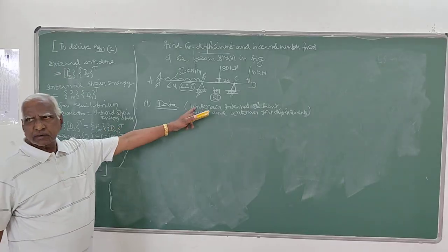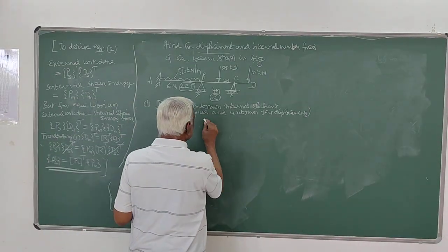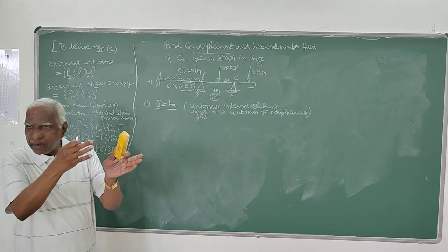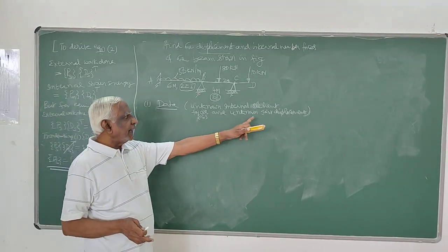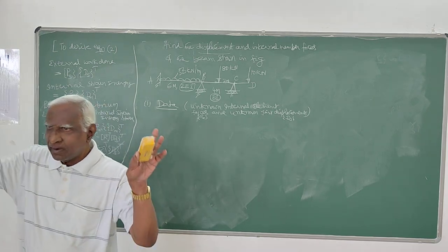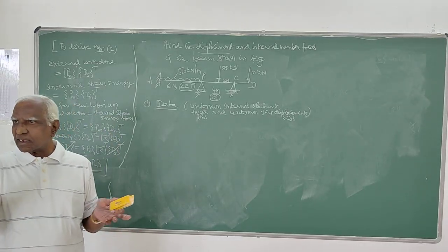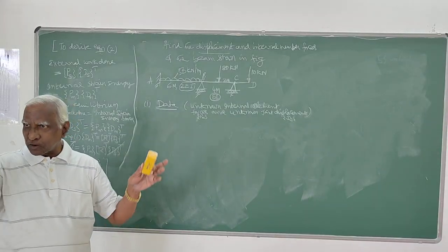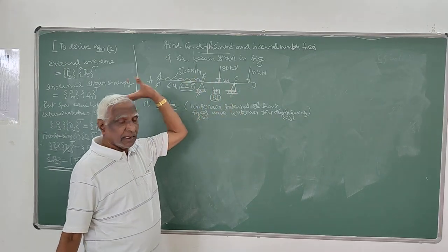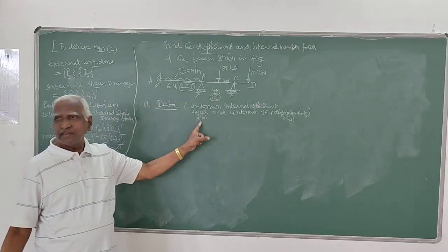That's what we have to determine. The data for calculating the unknown internal element member forces. Element member forces means it is PM. Correct? As per our notation, PM is the vector of element forces. And unknown joint displacement is ds. Always displacements will be measured at joints. Loads also will be considered only acting at the joints or nodes and the corresponding displacement. Since loads will be in the global direction, displacements also have to be in the global direction.